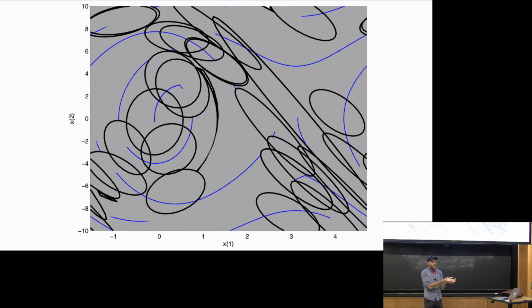This comes up with a sort of hybrid, switching into these different controllers automatically with only smooth analysis on the smooth system. There's something I think that's maybe good or right about the system having made a discrete decision by virtue of being in one of the funnels. You notice the funnels overlap, and the rule is once you're in a funnel, you keep executing that funnel until something kicks you out and your model was wrong, and I have to do something else. So there's some integer state there, some discrete decision that was made to be in this funnel, and this is what I'm doing right now. I don't know simpler ways to encode that, but I think it's important.